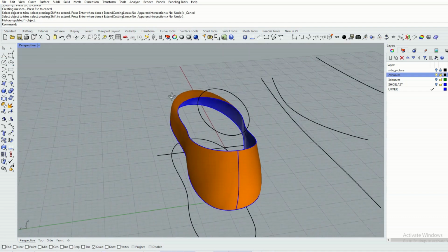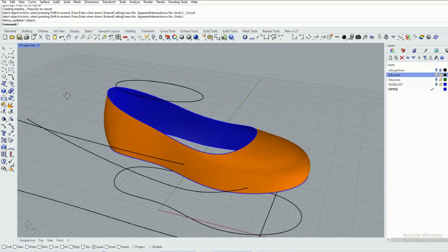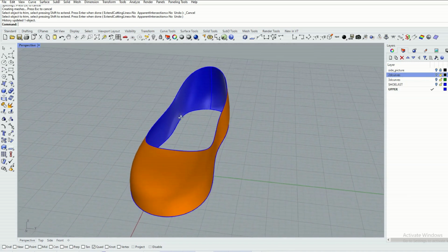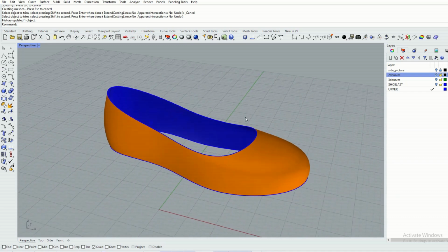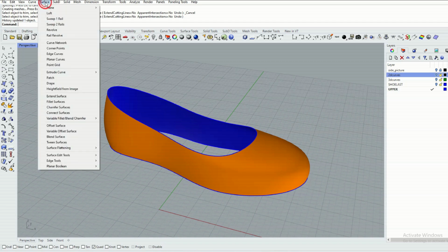I hide the layer with the 2D curves again and can simply develop the surface on the plane with the surface flatten UV surface command, unroll surface UV, which after some experimentation will prove to be the most correct type of development compared to developable surface, squish and smash.